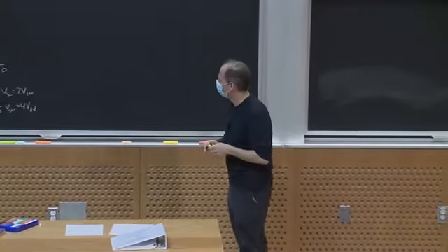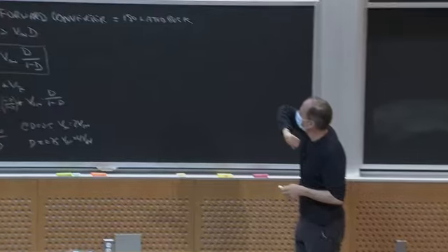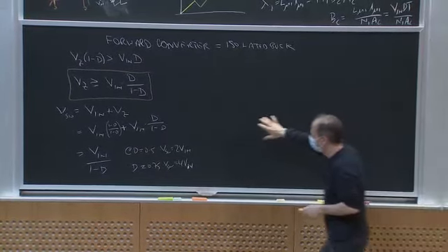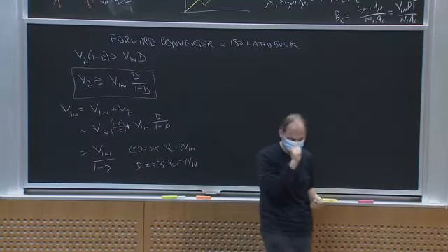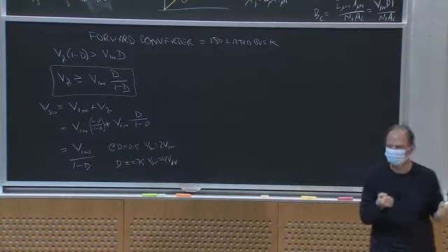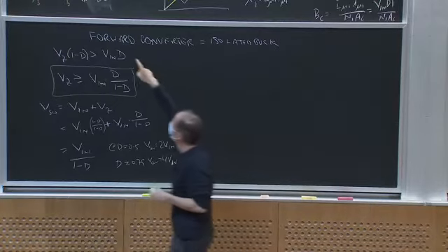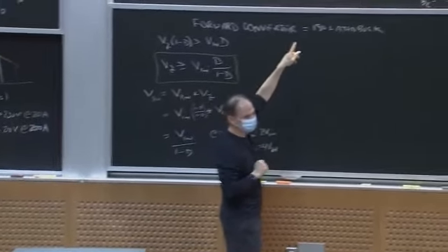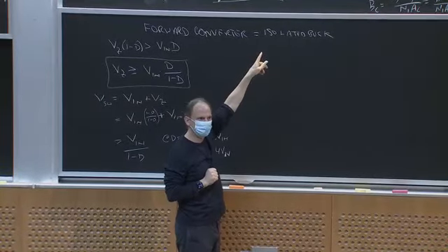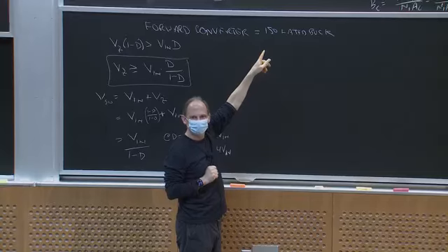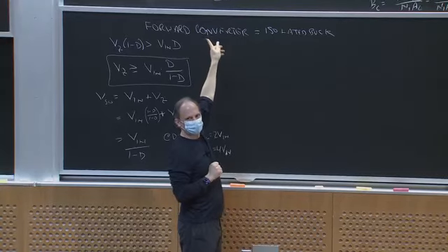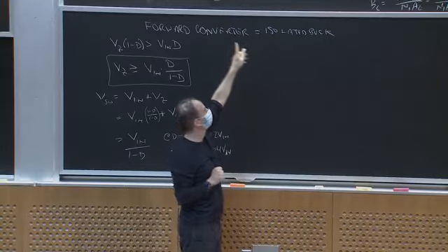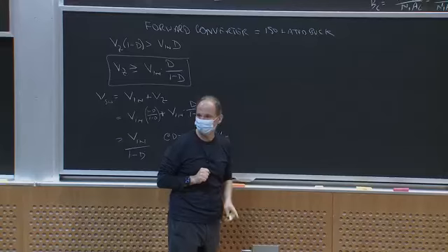Okay, let me just come back to this means of resetting the core, right? So we've reset the core, we have increased voltage stress on our switches. The other thing we have is increased dissipation, right? Because what am I doing here? Every cycle, I'm storing a little bit of energy in that magnetizing inductance. Magnetizing current ramps, so I put energy in the magnetizing inductance. What do I do with that energy? I dump it into a Zener diode. I throw it away, right? So I hate throwing away energy, but that orange circuit is throwing away energy.